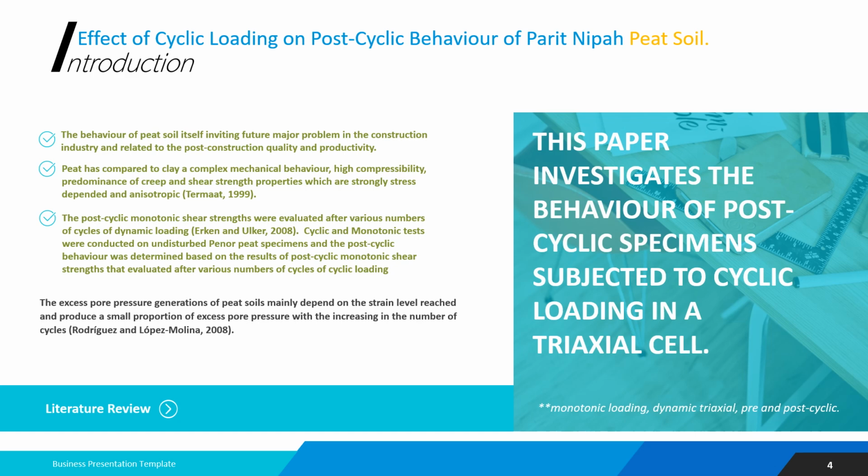The post-cyclic monotonic shear strengths were evaluated after various numbers of cycles of dynamic loading, according to Erkan and Ulker 2008, and as the amount of effective stress increases, the deviator stress also increases with the increasing axial strain, according to Paskowski 2003. In this study, there are three stages of testing carried out. First, static monotonic loading. Secondly, cyclic loading. And third is post-cyclic loading. At this stage, similar applications to the static monotonic test stage were adopted.